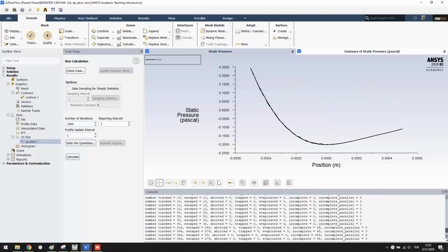To see if there is any flow separation or not, we can have a look at the path lines. Let's first create a vertical line upstream of the cylinder to release the path lines. Under Results, right-click Surfaces, and select New, and Line Rake.